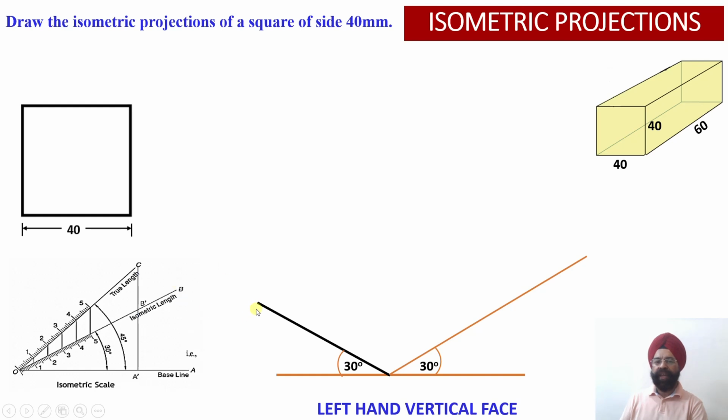So facing left orientation. Now here 40 millimeter has been marked. Once again, the isometric length of 40 millimeter has been marked corresponding to one edge of the side face. This side face will be contained between, as I have explained to you, the X axis and the Y axis, because the prism is left facing. So now this is 40 millimeter drawn on the X axis, this is 40 millimeter drawn on the Y axis, and now two more isometric lines will be drawn parallel to the isometric axis to complete the side face of this particular square, right?